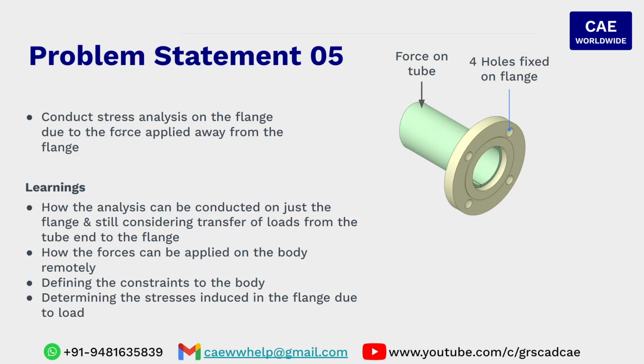The interest here is stress analysis on the flange only, meaning the consideration of the tube may not be required. The learning here is how the analysis can be conducted on just a flange while still considering the transfer of load from the tube end to the flange. How forces can be applied on the body remotely by using the specialized boundary condition loading commands in ANSYS. Defining the constraints to the body, that is, fixity at the mounting locations, and how to determine the stresses induced in the flange due to load, and post-processing of the results.